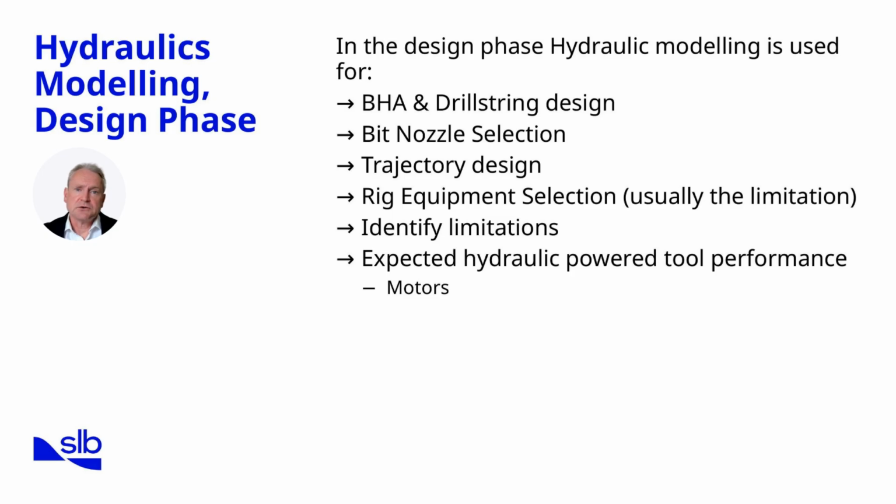Trajectory design is also informed by hydraulics. Different well inclinations and depths change annular velocity and equivalent circulating density, so simulations can identify high-risk sections where pressure or hole cleaning may be problematic. Rig equipment selection comes into play when we compare modelled requirements with the rig's pump capacity and standpipe pressure limits. Often this becomes the practical constraint.